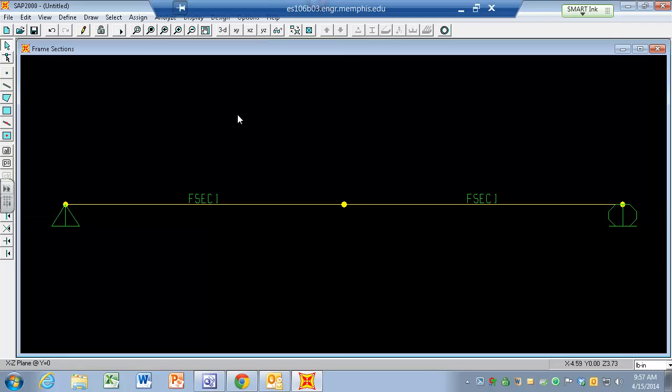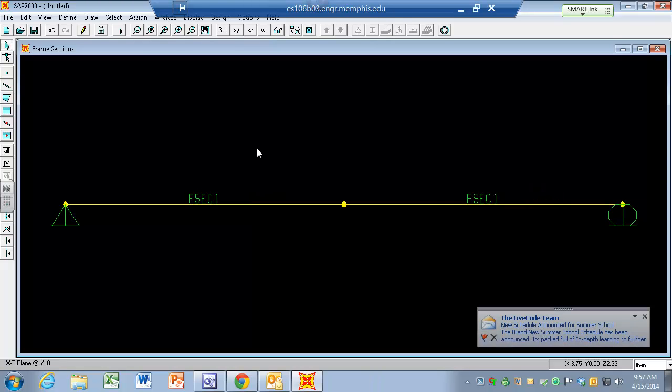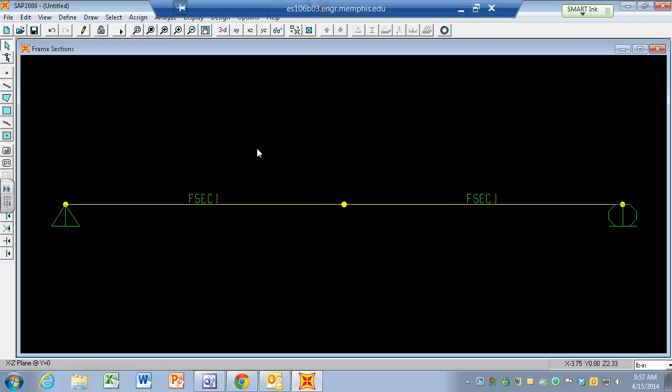Okay, so what have we not done? We don't have any loads on it yet. So what are the loads? Remember, they're 150 pounds distributed over the middle 6 inches. So that is a uniform load of 150 divided by 6, which is what? Someone got a calculator. 150 divided by 6 is 25. 25? It sure is. Yeah. That's convenient. So 25 pounds per inch is the intensity of the load.